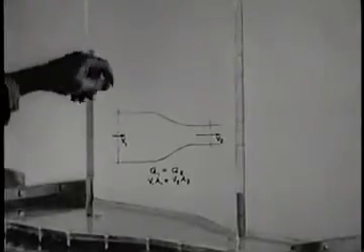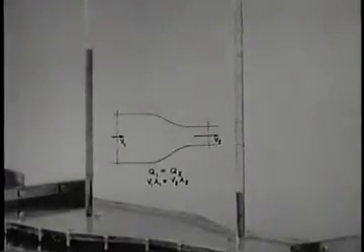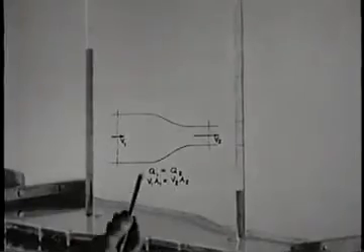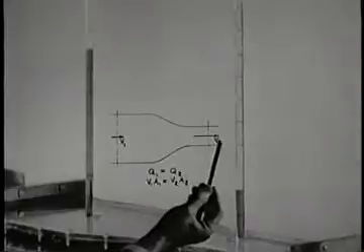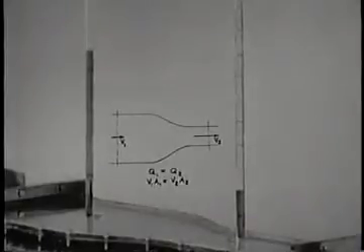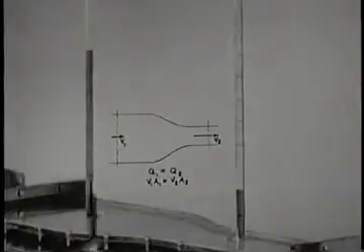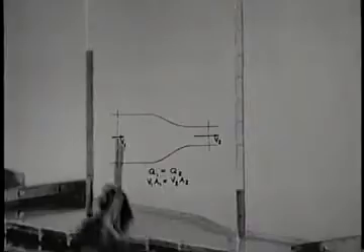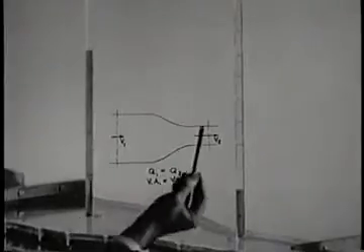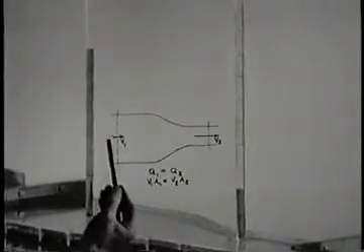What about the velocity of the flow? Since water is nearly incompressible, the volume flow entering the contraction must equal the volume flow leaving, or else mass would be created or destroyed. But the volume flow is equal to the average velocity times the cross-sectional area, so the area decrease should produce a velocity increase.